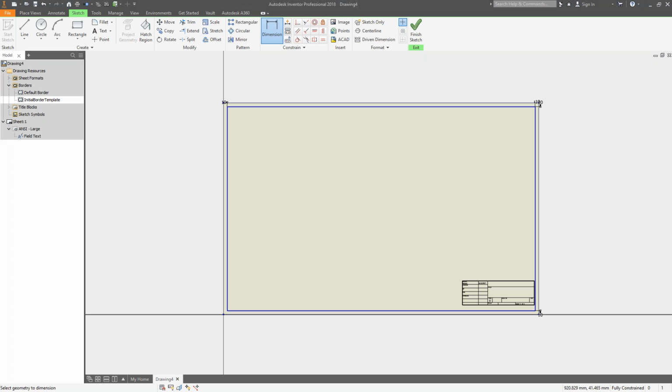There's no text, there's no black arrows, there's none of that. So if I wanted to add in some additional information, maybe some match lines or some zones, you would just come in here and sketch those just the exact same way you would any other thing. I could come in here and create these. I'll add a few zone lines. So I'll snap to that midpoint and to there. I'll do the same thing over here, midpoint and there, and same thing right here, midpoint and there. So now I have these four zones, my super simple.